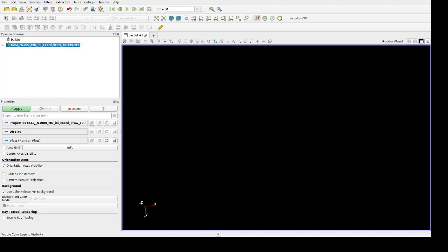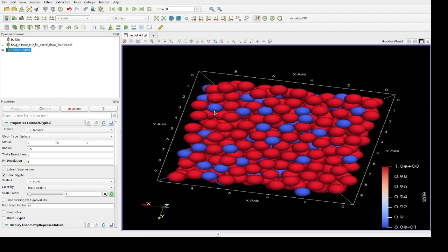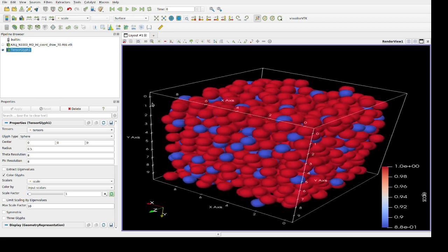In the last step, you need to load the processed VDK file and run the macro in ParaView, and the visualization is complete. You can load your data from File and press Apply. Then, on the loaded data, you want to apply the Python macro for visualization. And the visualization is complete.